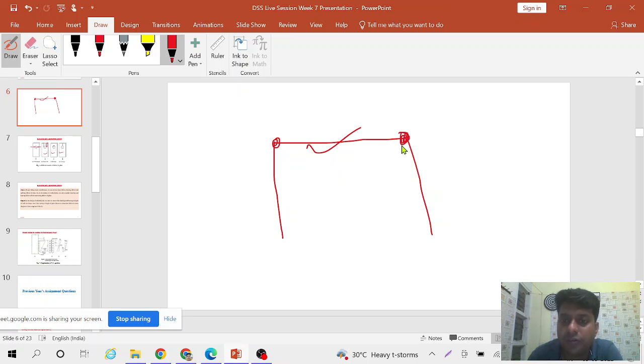And falling of this member can lead to, what you can say, it costs life. Means if anyone is standing below this member, then he will die or be badly injured. So that is why we provide a very good strength in the connection. So in practical cases, we want that before connection failure, this member will bend, means try to deflect, or it can show some failure symptoms,